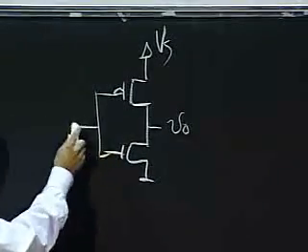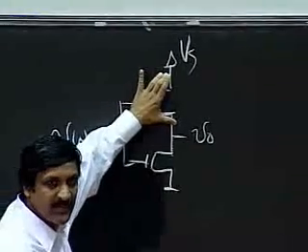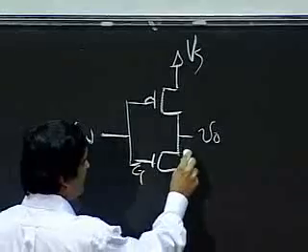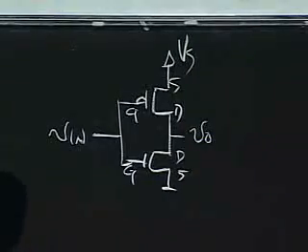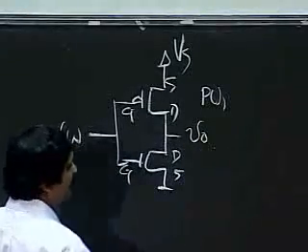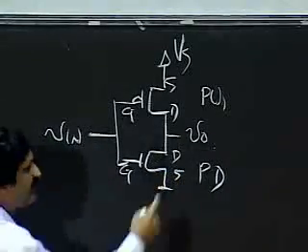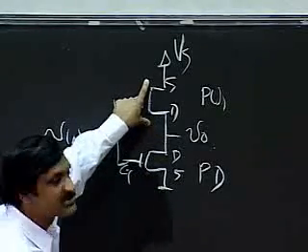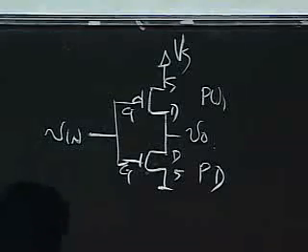Okay, and that's it. So all I've done here is replaced my resistor with a MOSFET that behaves complementary to the N-channel MOSFET. So this is my gate, my drain, this is my source, my gate, my source, and my drain. Okay? And this guy is called a pull-up, and this guy is called a pull-down. Okay, and the reason is that this guy pulls the output to ground when it's turned on, while this guy, when switched on, will pull this node up to Vs. So I pull it down or pull it up based on whether Vin is high or low.